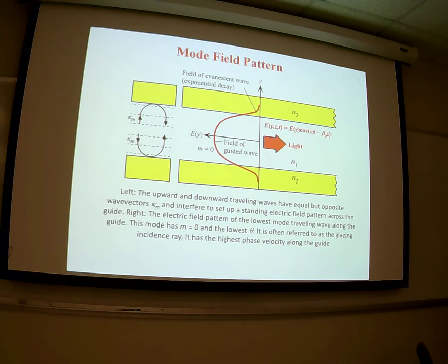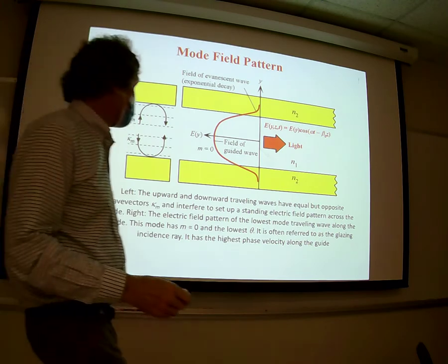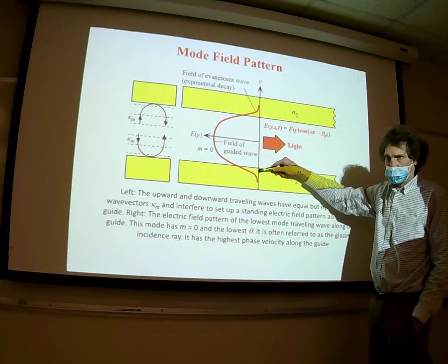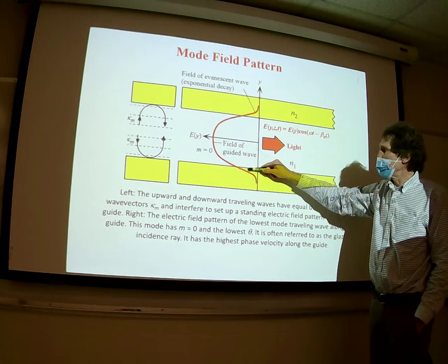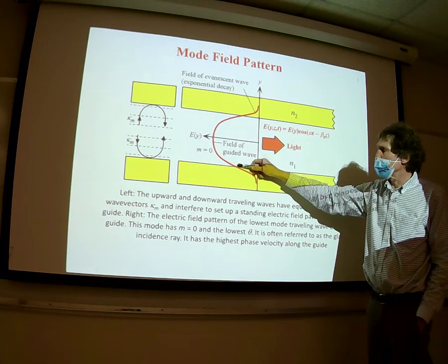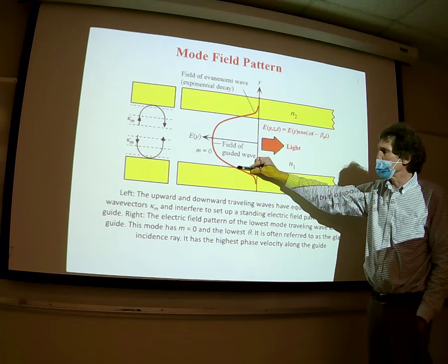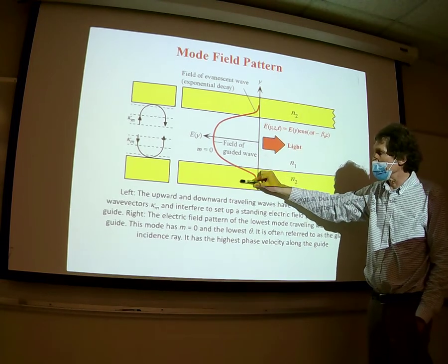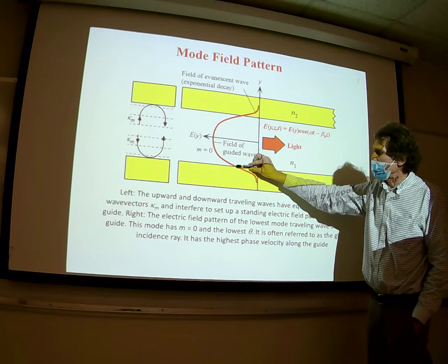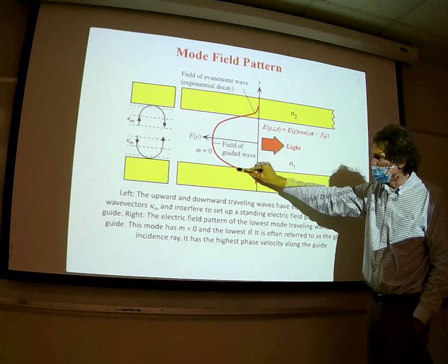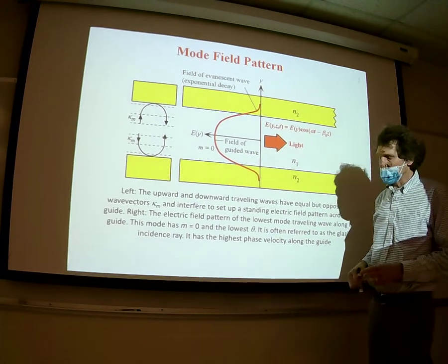This is what I wanted to talk about. Now, this is a perfect picture of the zero mode, where you have a half wavelength basically across here, right? Half wavelength right here doesn't go to absolute zero. It's equal to what's called the evanescent mode that's going this way. This mode will die out real quick. So what they do is match the boundary conditions for the tangent electric field there, at this point, with this point, and then they go through and get a solution.